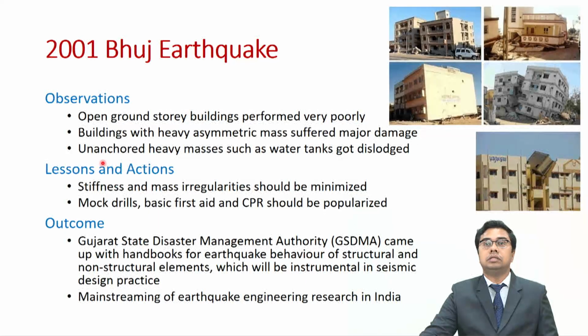So, this also means unanchored heavy masses such as water tanks got dislodged. From this earthquake observations, we have learnt a lot of lessons. The first thing is that, very similar to some of the previous earthquakes, stiffness and mass irregularities should be minimized. We will learn more about these irregularities in the upcoming class, so that we can avoid these irregularities.